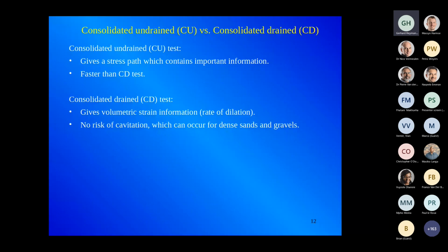When would I actually prefer to do a consolidated drained test? And there's a few instances. One of them is when we test a dense sand or a dense gravel. Why? It's because a dense sand or a dense gravel dilates so aggressively that before long your pore water pressure goes negative, reaching cavitation.